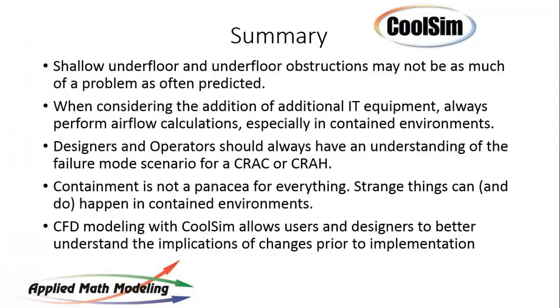And I would never advocate both hot and cold. Is that consistent with your thinking too, Lauren? Yeah, I've never done hot and cold in the same data center hall. I think there's probably some situations where you could do that, but you'd almost carve out a specified area for that and make sure that you have the recirculation. It's all about getting the right amount of air in front of the servers and then removing it on the back end. Right.